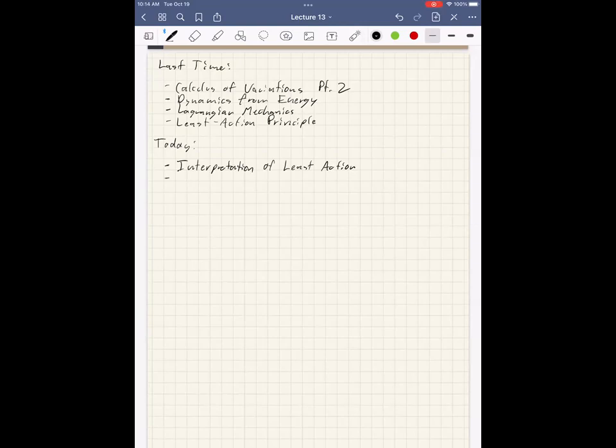So today we're going to look at the Manipulator Equation, which is the form of this stuff that you most often encounter in robotics. But it really is just the Euler-Lagrange equation reworked and relabeled. So we're going to derive that and talk a little bit about it.